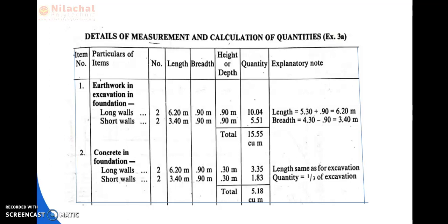Then the breadth of the long wall, how can we define? First of all, we need to define the breadth of the long wall, then we can calculate the length. We know that in excavation there is no particular depth, so the depth of excavation we consider on the basis of the bottom part of the foundation.